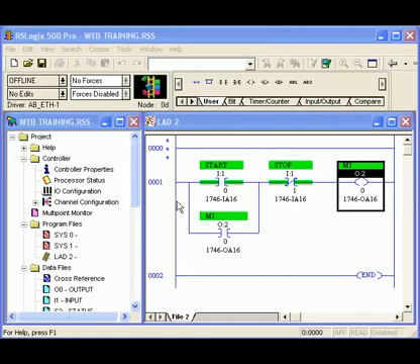You look at the power coming in on this side, traveling through contacts and operating a coil, and finally making it to neutral. So if you understand electrical circuits, then you'll understand that this is made so power flows, this is made, power flows, okay, this coil should be on.